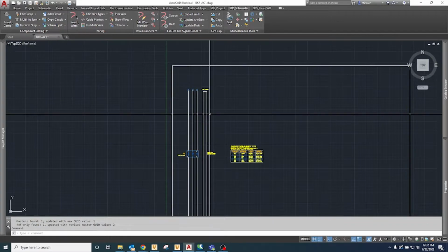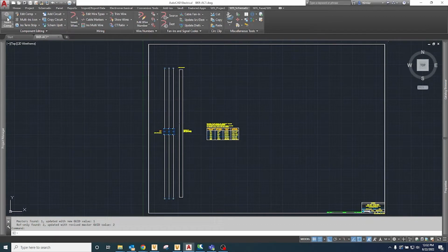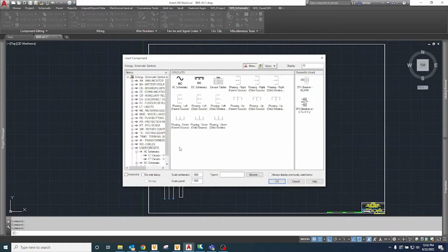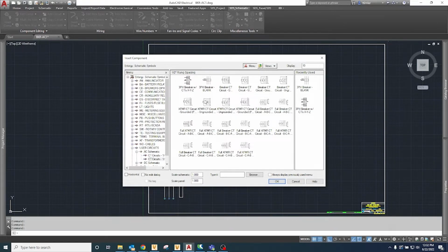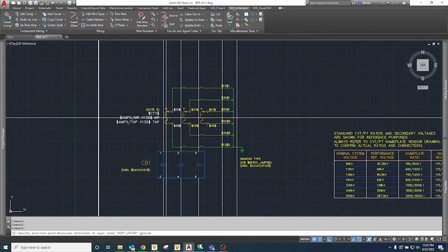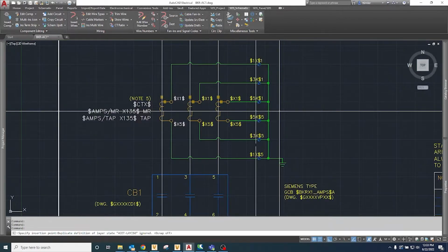It's good right there. Now I'll return to the icon menu and select User Circuits again and start placing some bushing CT circuits for this breaker. Under AC, I'll go with a 1/2 inch spacing option. I'll make this first bushing CT a shorted and grounded CT. Keep my options checked. And then just find a position on the bus and drop it in.